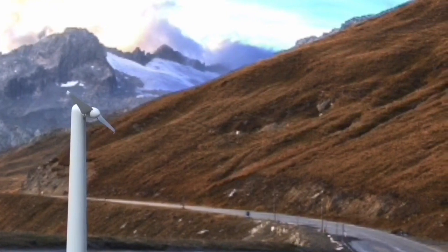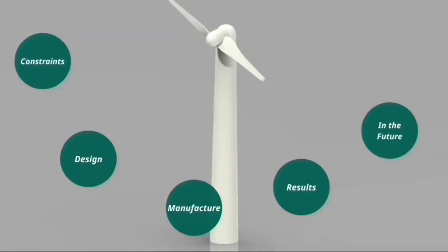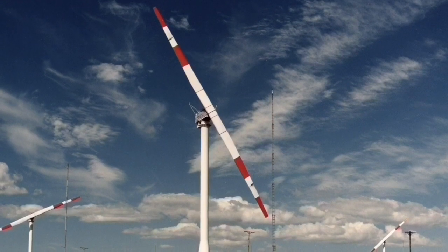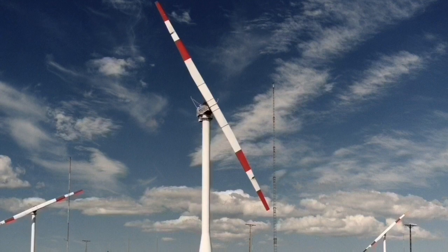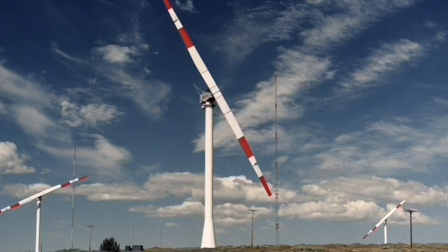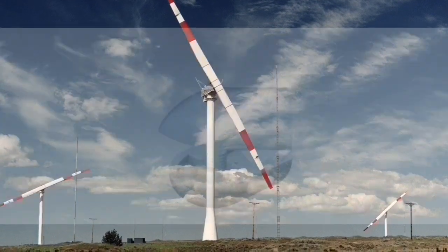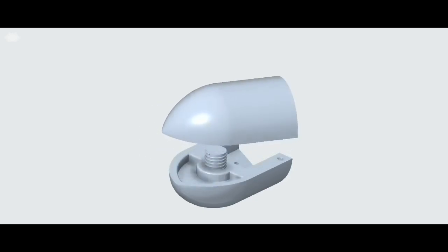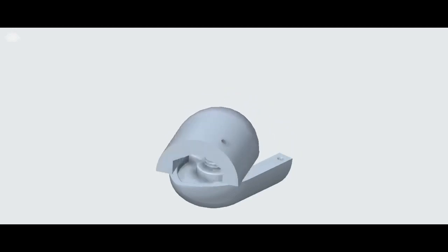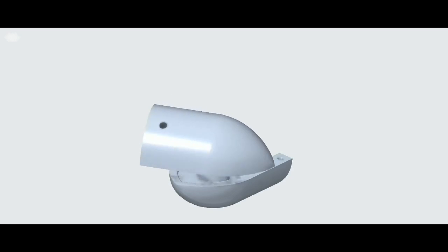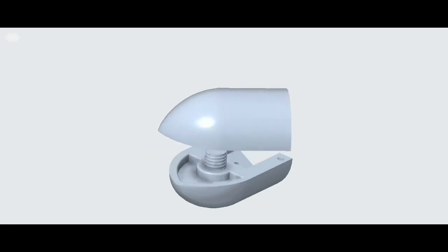Not letting the pandemic slow our engineering spirit, we put some thought into some future iterations. We'd be keen to investigate the possibility of removing the nose cone altogether from the design by blending the opposing blades into a single smooth joint. This could further reduce drag and moment of inertia costs. We could optimize the design by removing hinges altogether to reduce the number of possible failure modes. This could be replaced by a screw mechanism binding the two halves of the turbine together. Here, friction alone could replace the need for costly adhesive.